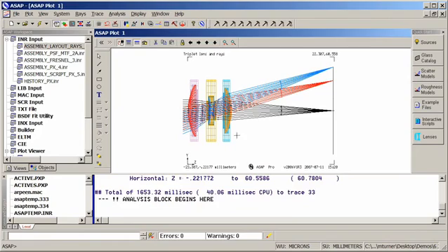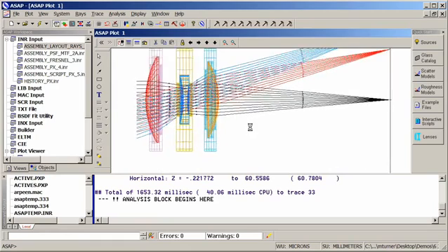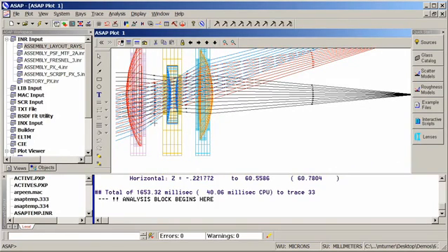The first is to look at our detector surface here, and we can see that indeed it appears that each of our sources is being properly imaged on this detector surface. But I also want to scroll in a little bit on this design, and concentrate on this area right here. You'll notice that these two rays, one from the blue edge of field point and one from the red medial field point, actually intercept the mechanical retaining ring. They don't propagate all the way through our optical system.